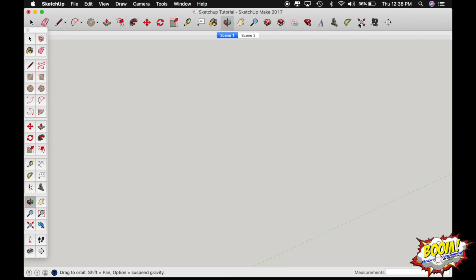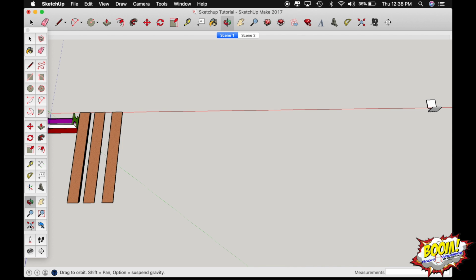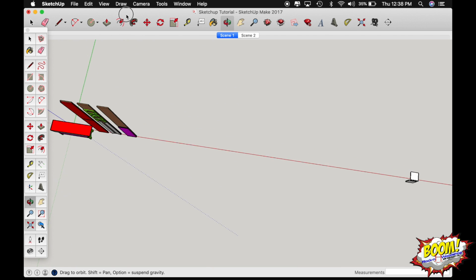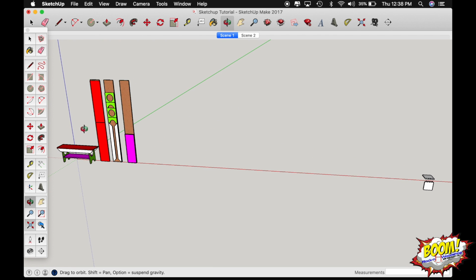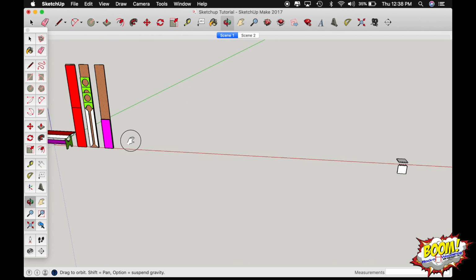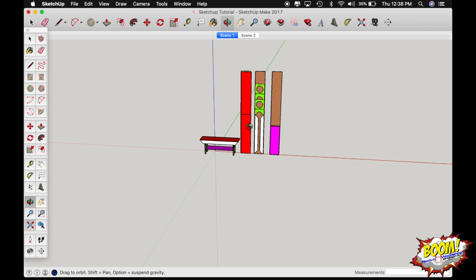There is an icon that you'll find here that I added to my toolbar, or in the large palette, it's down here, and if you hover over it, it's called Zoom Extents. And if you click on it, it will take you back to the portion of your screen where all of the projects that you have on that screen are centered. Now, I've added a couple of things to mine, so it's going to show it off a little bit. So there it is. It has centered back everything that is in my project. I can kind of reorient myself to where it's at. And I've got something else that's added over here. I'll have to show you a little bit later. But that's how to get your project back in the viewfinder window very, very quickly.